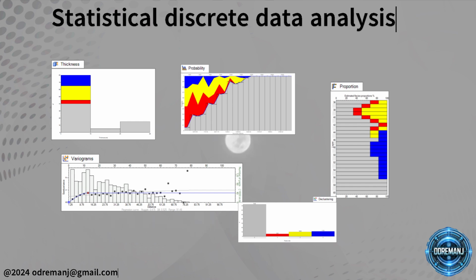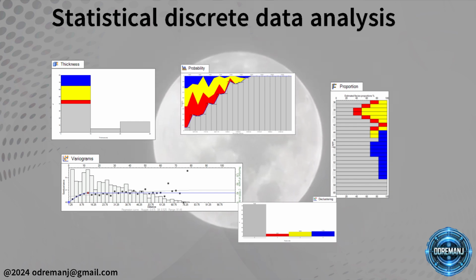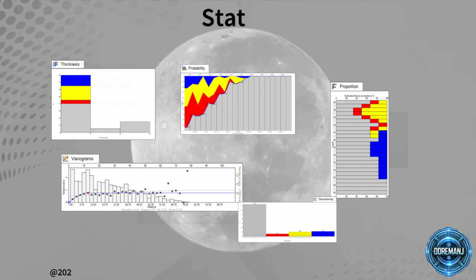The data analysis results combined with the conceptual sedimentological model can build a more realistic facies model when used in the facies modeling process. This analysis is the first step in facies modeling. You can perform it when an upscaled facies property is available.